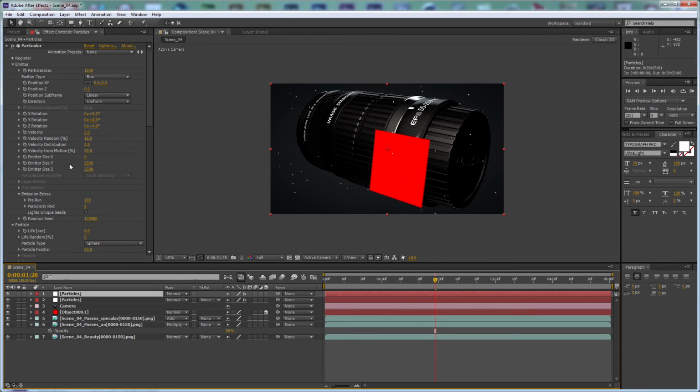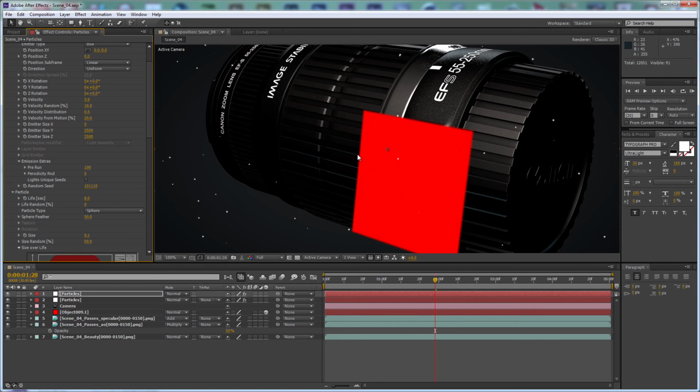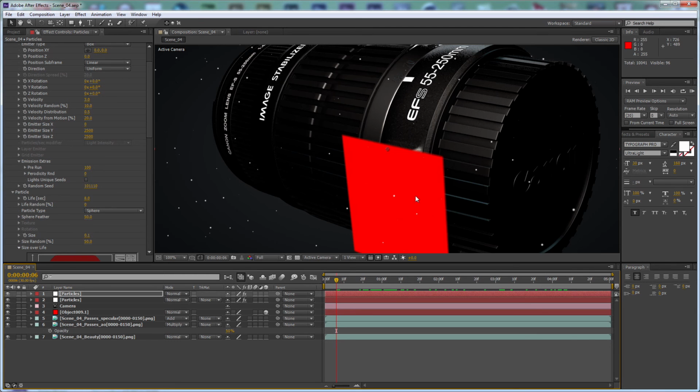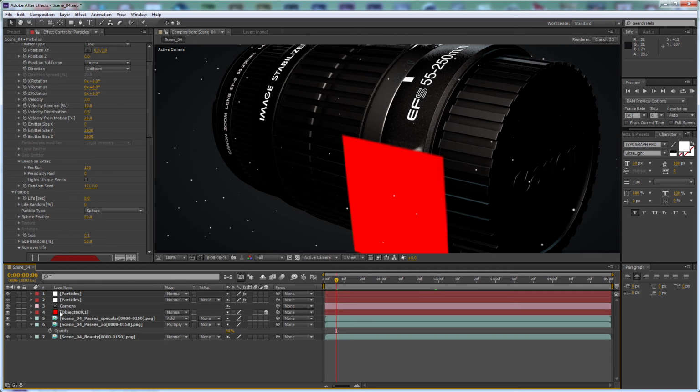And these are the large particles. We need to make a copy of the layer and just change the random seed, increase the number, and reduce the size to 0.1, so they are almost invisible. Don't know if you can see it on the screen capture. And those are the particles we have.